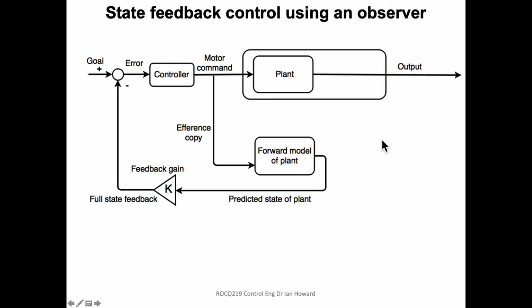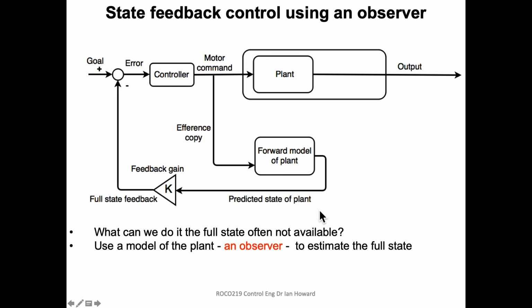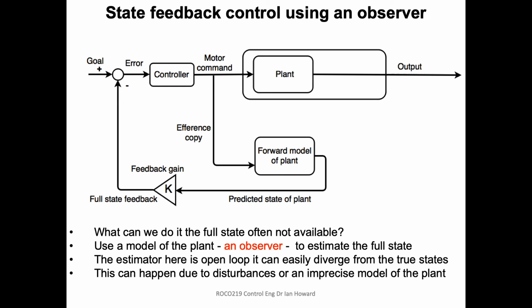Now, obviously, this is a feed-forward controller, right? We're not actually doing anything. We're not looking at the output at all from what's happening here and affecting anything that's happening down here. So that's got its issues. If this model of the plant differs a lot from the plant, then this isn't going to work very well.